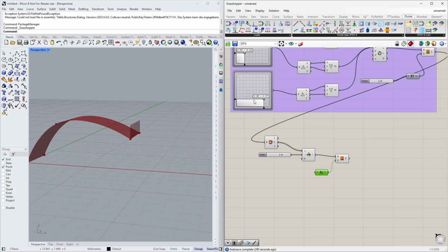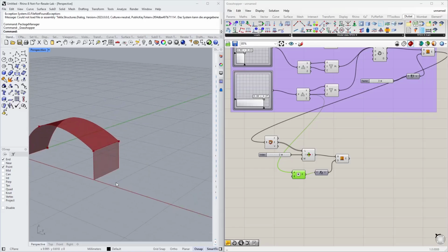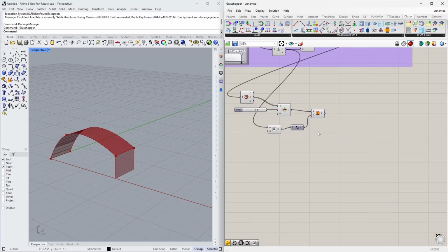And the coordinate itself comes from my arc or my curve that I defined in the beginning. It's the Z component or Z coordinate of that node. So obviously the Y coordinate here and multiplied by -1. So we make a little multiplication component. And then it always has the right height. Yeah, so even if I play with my MD slider, the wall always gets the right height at the end of the day. All right, that's the first part.